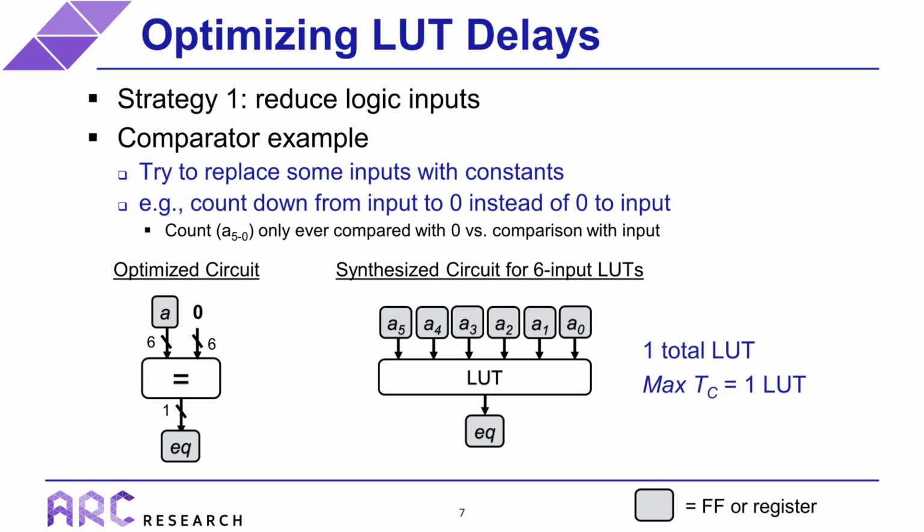So let's say we have this counting circuit and it needs to count some number of times, where that number is specified as an input that gets stored into a register. So it's basically a non-constant input. And let's also say that both the input and the count itself are both 6 bits. Now, one very common way of implementing this circuit would be to count from 0 up to the number stored in this input register.